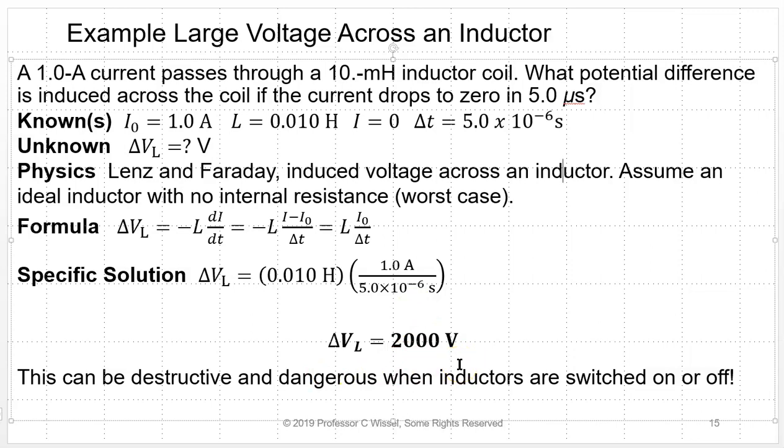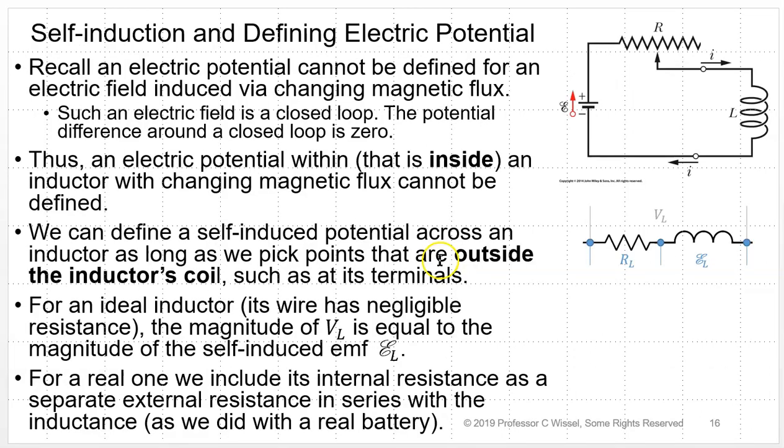This can be very destructive when inductors are switched on and off, especially repeatedly, and especially if you have a motor carrying a heavy load, like a compressor in a refrigerator. Or a pump, like a well pump or a sump pump. Okay, so self-induction and defining electric potential.